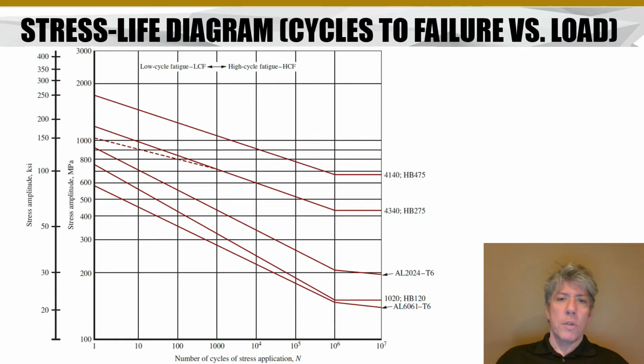A lot of engine components in your car have to be designed to last forever, if they're going to last at all. Because really the number of cycles required before you get to this infinite life section over to the right, where the curve tapers off and it's just a horizontal line, that many cycles is not all that large. You see it listed here as 1 million. The data is nowhere near this clean. These are average lines from a bunch of experiments.